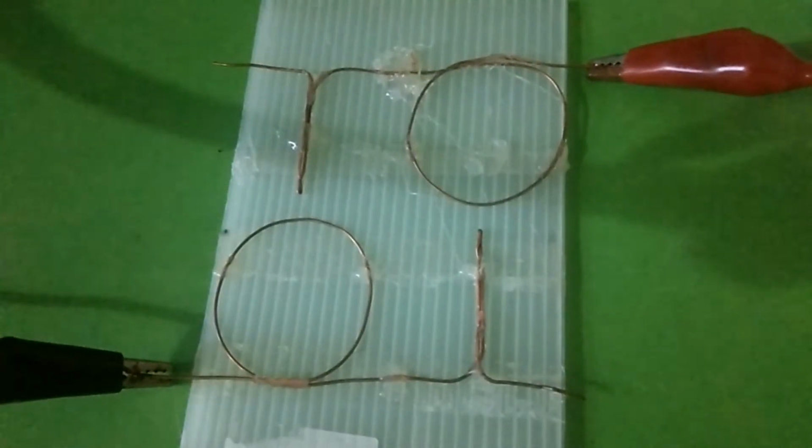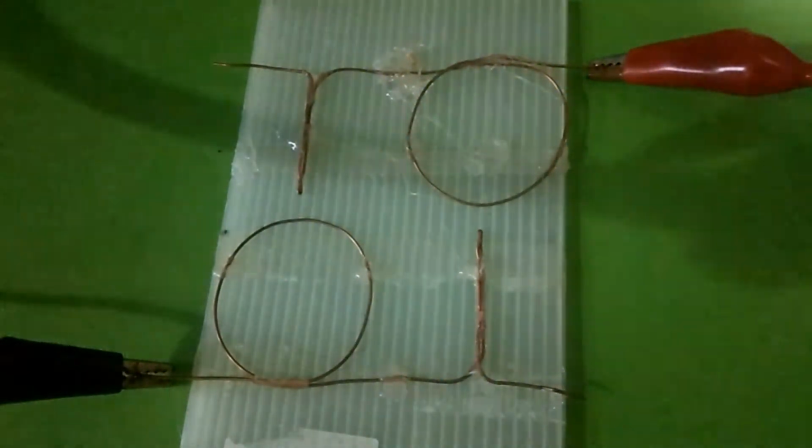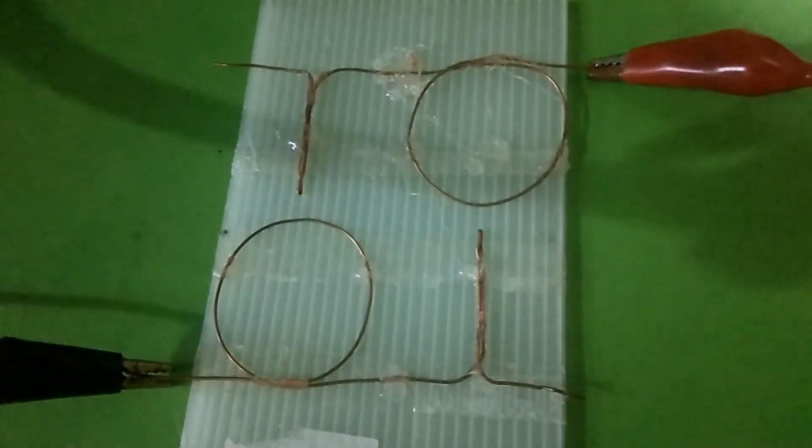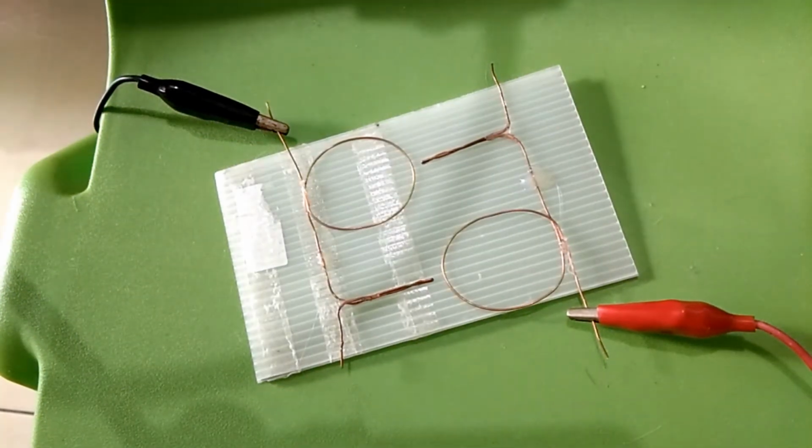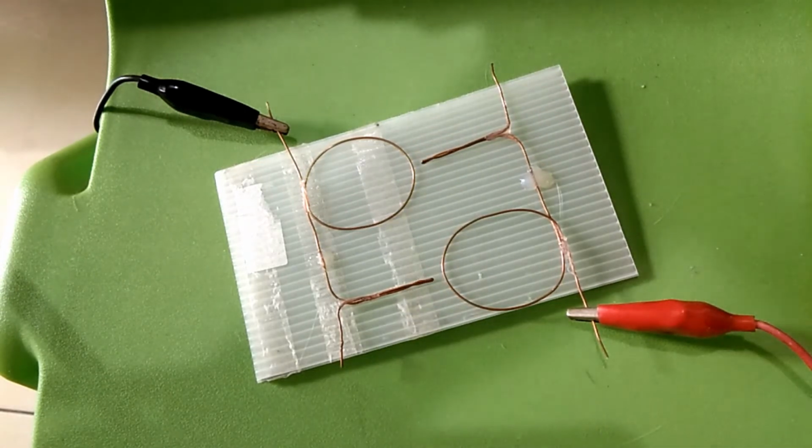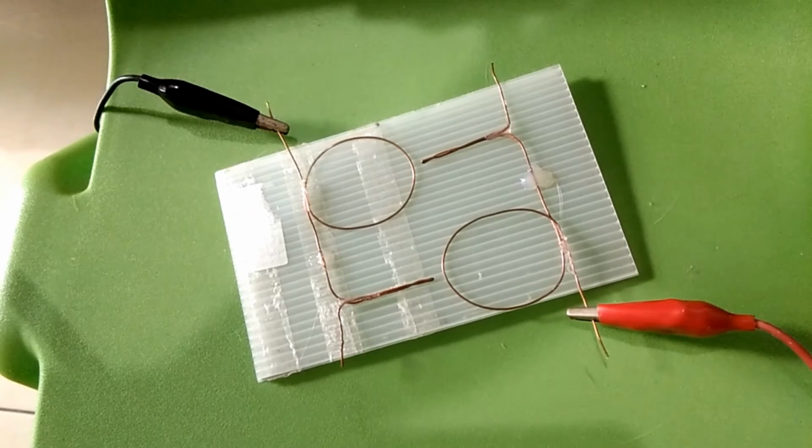Now the electrodes have been rotated 180 degrees. This time the spark occurs on the gap where positive voltage is connected to the blunt electrode, which means it is the same gap that produced spark previously. Let's repeat the last setup, but the blunt loop wire of the negative electrode is slightly deformed to reduce the gap. This time the spark occurs on the gap where positive voltage is connected to the sharp electrode.